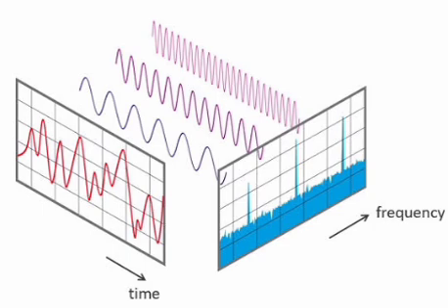Properties of the Z transform. Linearity: a x1[n] plus b x2[n] corresponds to a X1(z) plus b X2(z), with ROC containing R1 intersection R2. Time shifting: x[n - n0] corresponds to z^(-n0) X(z). Scaling: a^n x[n] corresponds to X(z/a), a scaled version of R. Time reversal: x[-n] corresponds to X(z^(-1)), with inverted R. Time expansion: x_k[n] equals x[n/r] if n is a multiple of r, and 0 otherwise, corresponding to X(z^r).